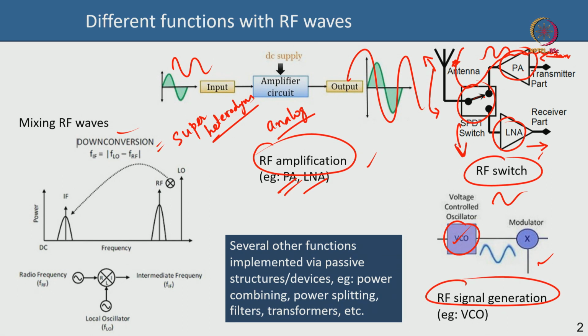What happens is that when you are sending a signal, your voice or your image or video, it's a very low frequency signal, but you cannot send that signal out in space. Your antenna size would be enormously large, and it's not practical. So you need to modulate that signal onto a sine wave of a higher frequency, a radio frequency or microwave signal. There is amplitude modulation, phase modulation, frequency modulation, and much more complicated digital modulation schemes. You send it and then you receive it.